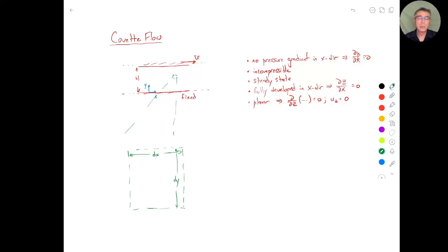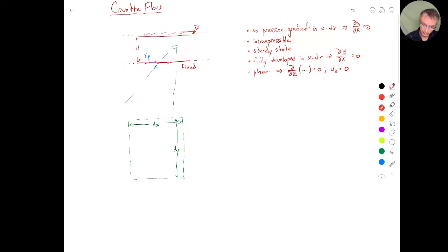And what we're going to do is apply conservation of mass and the linear momentum equation to that control volume. And specifically, it's really the x direction I'm interested in. But let's go ahead and apply conservation of mass first. Let me write out what conservation of mass looks like. I'll just write it over here. So here's my form of conservation of mass.